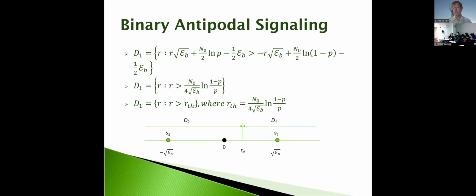That's limited by regulation, but I can achieve some pretty good signal to noise ratios, right? So the amount of signal energy relative to the noise, and therefore I can go up to like 1024 QAM type signaling. So I'm getting 10 bits per symbol through.